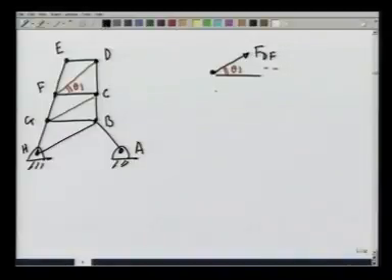Then this has a force, and in anticipation I am going to make the direction down, F_FG, and let us call this angle at which it is acting theta 2, and we will calculate its sine and cosine soon. Then in anticipation again, let me just anticipate that the force F_CF is going to be towards the left. So, this point F is in equilibrium under these three forces F_DF, F_CF and F_FG.